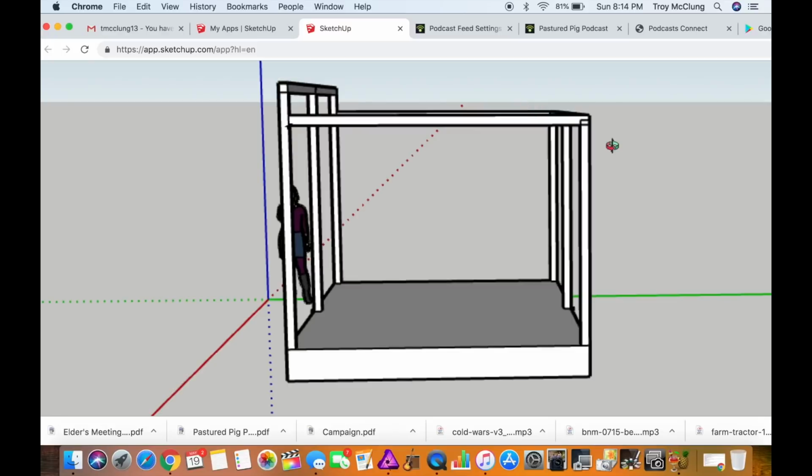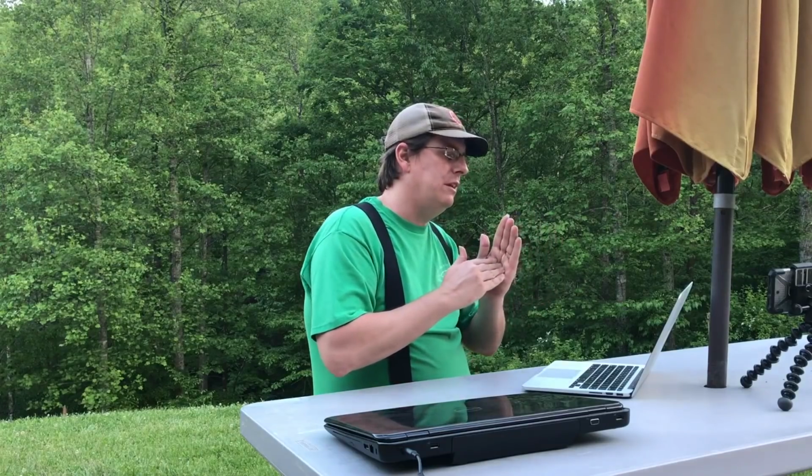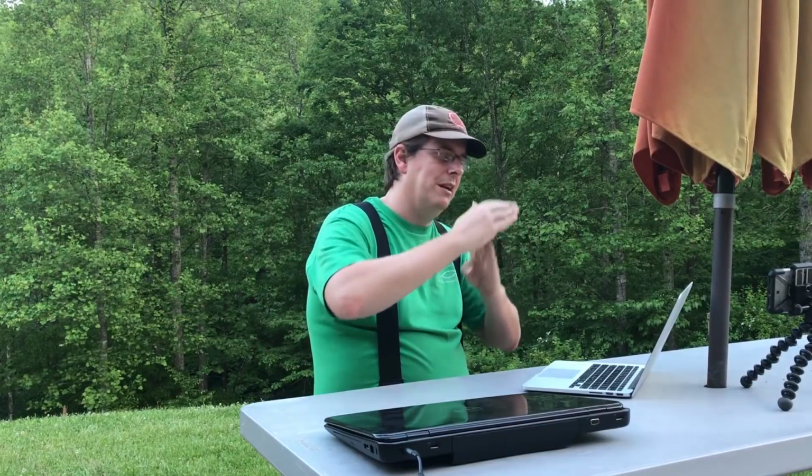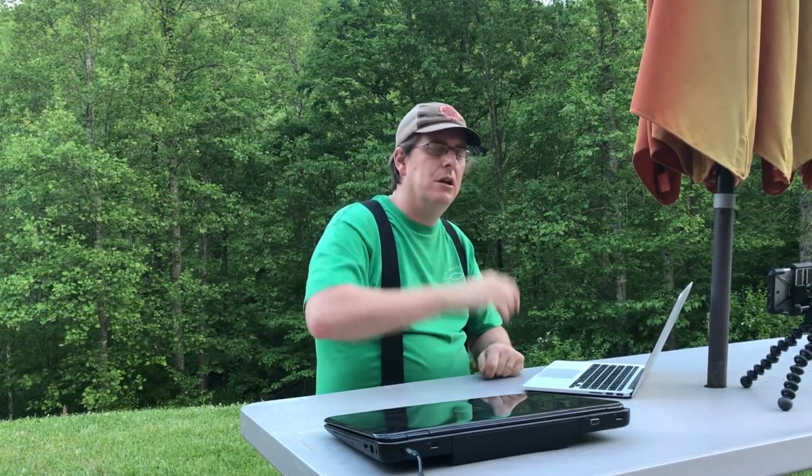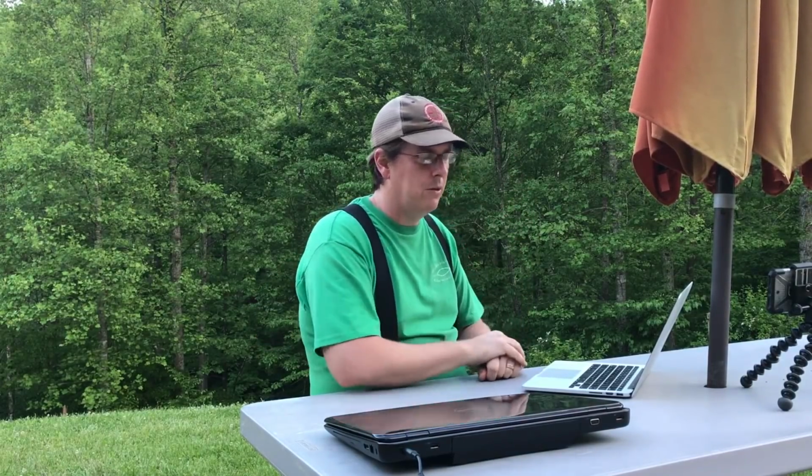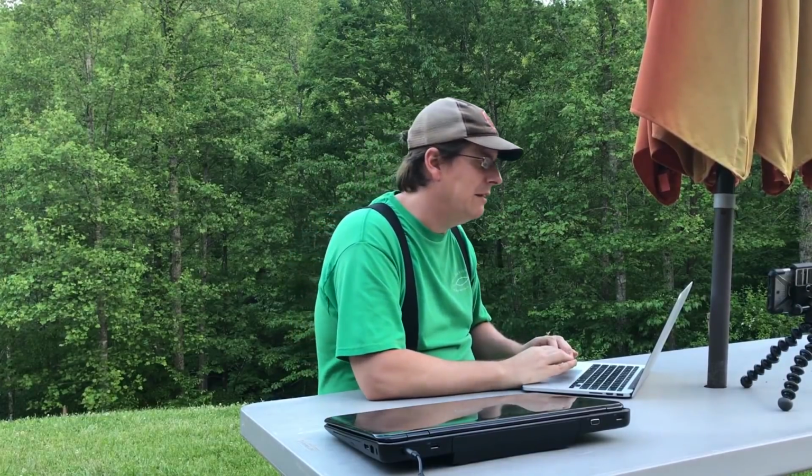And obviously we'll do some nice rain catchment off the back of that, because that's going to be a 12 by 20 metal roof there, so we'll have a lot of square footage to catch some rain. But where this horizontal is going to tie the back into the front, we're going to have it butting into the front post instead of putting it at an angle, because I haven't put my actual rafters and purlins to hold the metal roofing in the design yet.